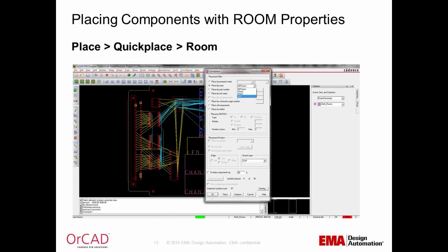The max uncoupled length is the maximum length in database units a differential pair is allowed to remain uncoupled. And the gather control with ignore or include allows the user to specify whether the differential pair length from the component pin to the gather point is factored into the DRC value for uncoupled length. The phase tolerance is the difference in the overall length between the two members of a differential pair. This constraint is available only in Allegro PCB Designer or above.